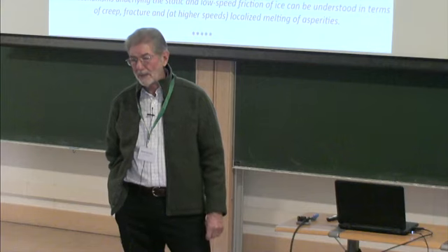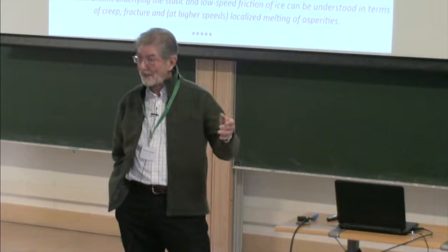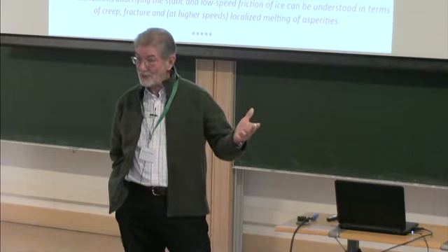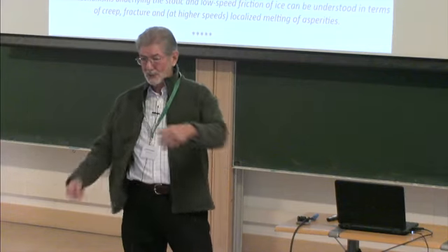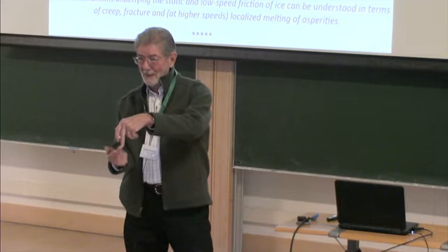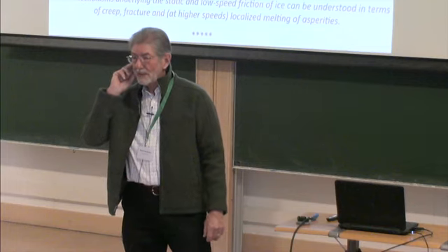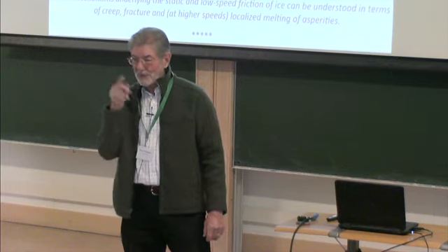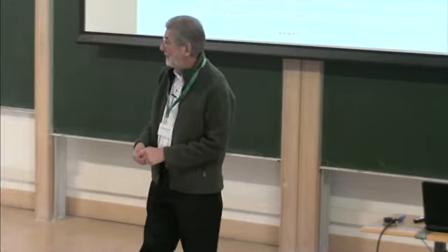Fracture, I think, may well be in there, because if you look at the hardness, the hardness comes to quite a high value at these rates. If you put the numbers in and you stand back and say, look, an asperity can't support that much stress, it's got to fracture. So I expect if we listen to this microacoustics, we're going to hear something. So I think fracture might be in there as well. More complexity. One more question.